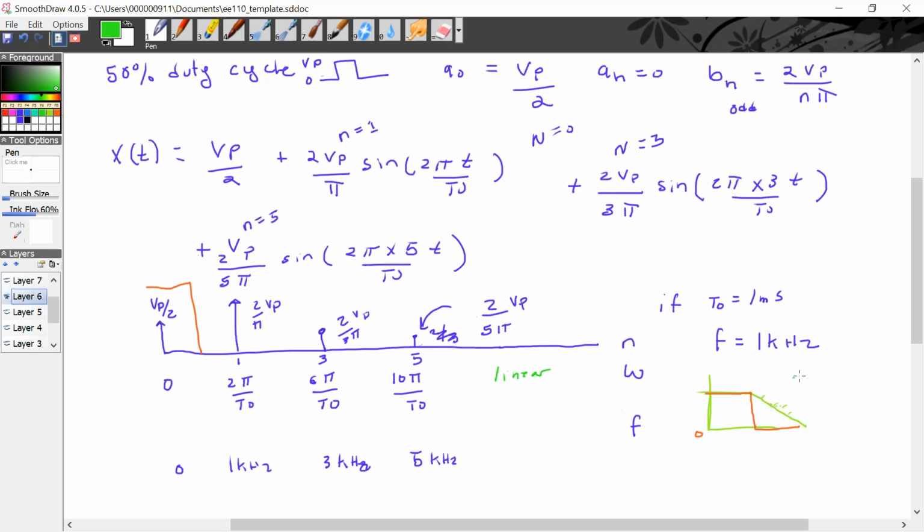In a linear scale, you're actually kind of getting this S kind of thing. And so to draw a real filter, I'd kind of get this. So that means I could pass up to here but I'm still getting some of that signal. Now, how much? Well, whatever the magnitude of the transfer function is, times whatever the magnitude of that signal is, is what you would be getting.